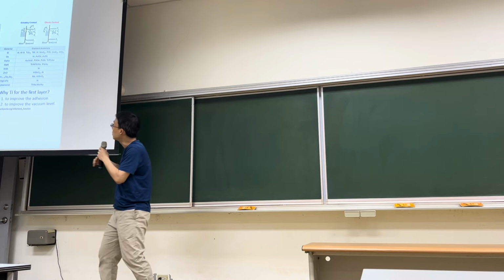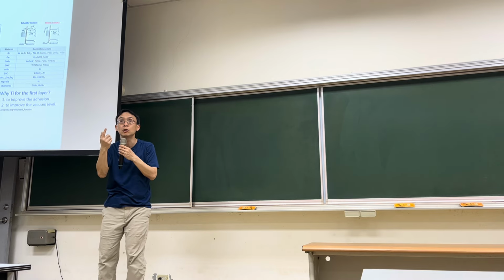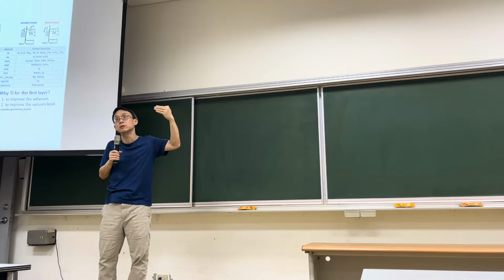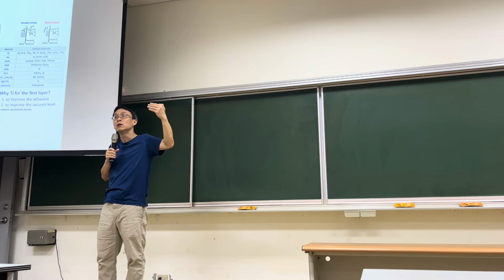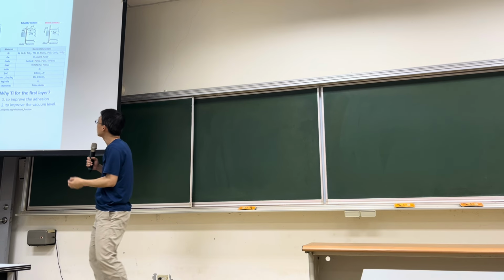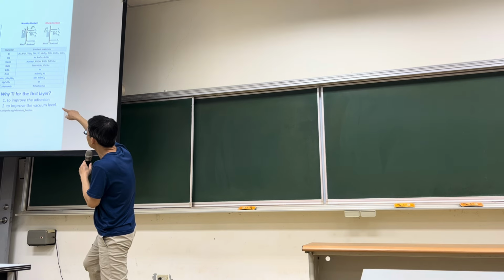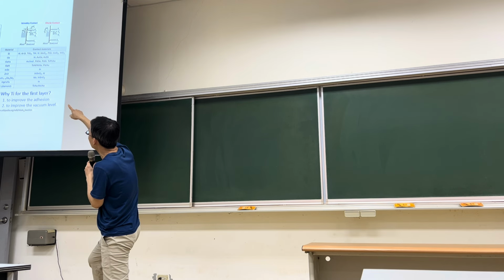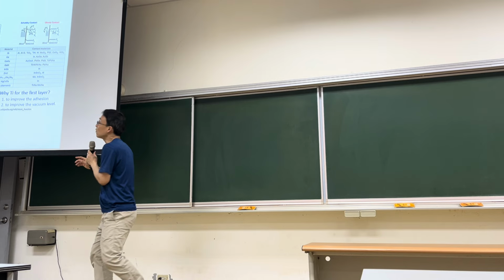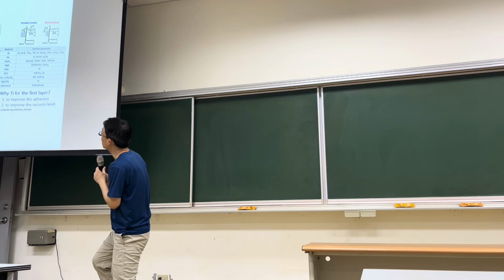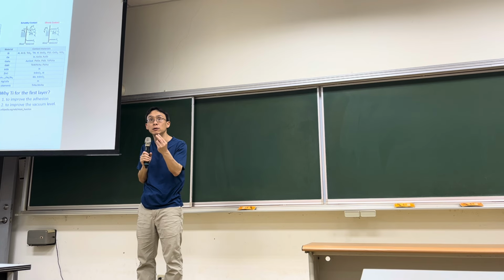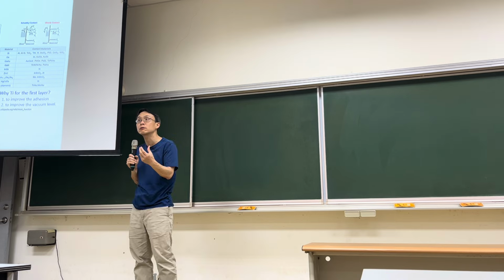So each of the values is showing the work function, right? Usually a work function above 5 is a large work function. A work function below 5 is considered a small work function, right? Those in the red box: gold, aluminum, nickel, palladium, platinum, titanium. The six metals in the red box are the common metals for you to form the electrodes.